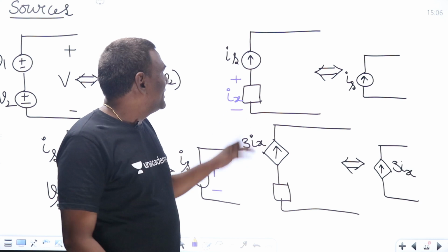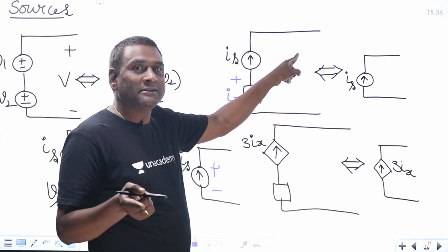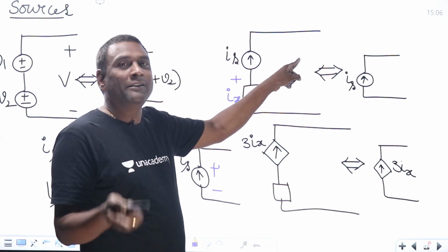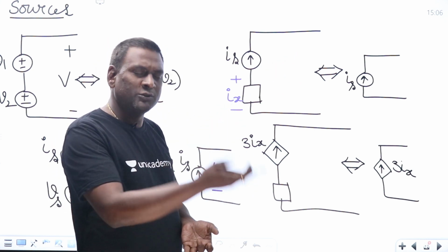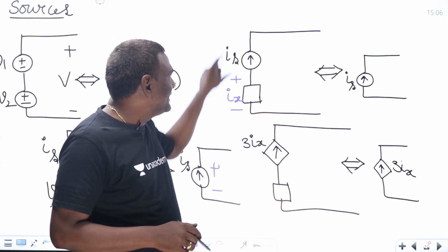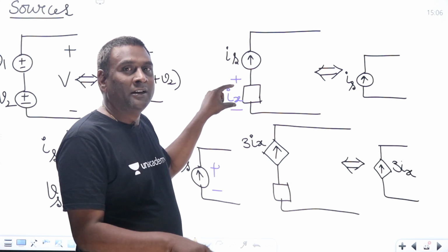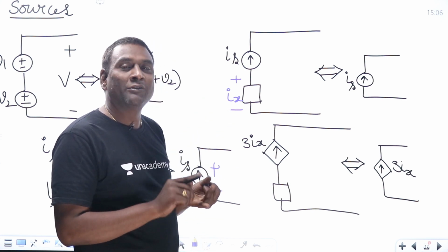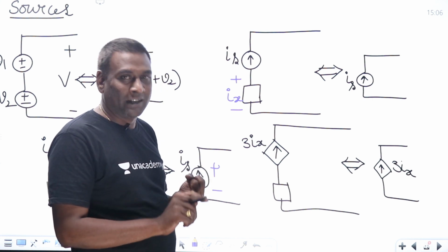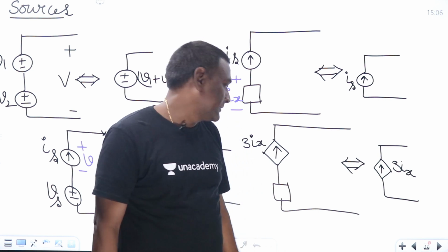Ideally, this is a current, right? Current is linked with KCL, which is linked with nodal analysis. Very soon it will come. The conclusion is very simple: anything connected in series with an ideal current source can be neglected while applying KCL or nodal analysis, provided some information is being asked external to the system.